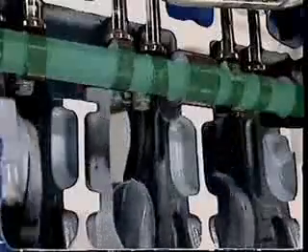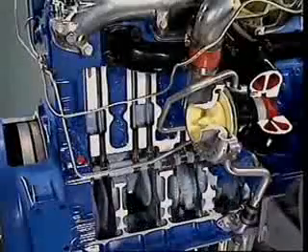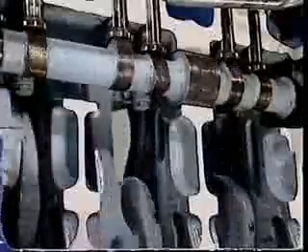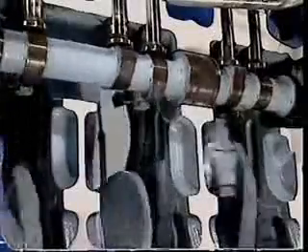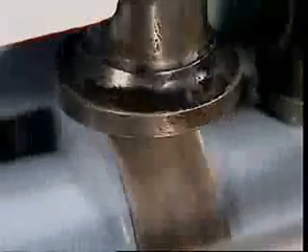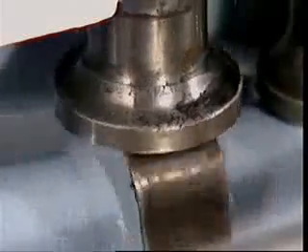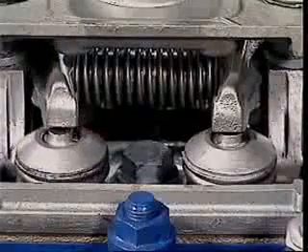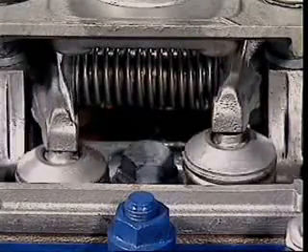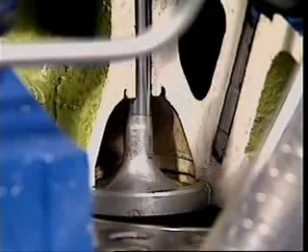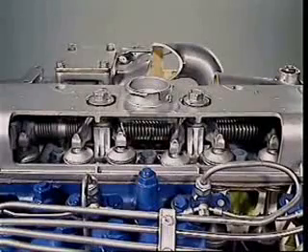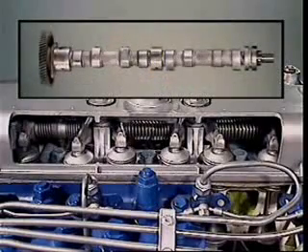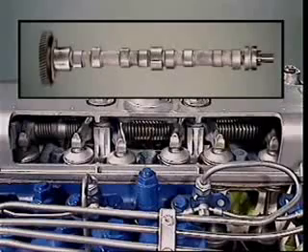In many diesels, valves are driven by a pushrod system. The camshaft is mounted in the engine block near the crankshaft and gear driven by the crankshaft. As the camshaft rotates, a cam bears against a cam follower that pushes up a pushrod. The rocker arm pivots and opens the valve. Some small, high-speed diesel engines use a camshaft in the cylinder head. This is called an overhead camshaft, and it's usually driven from the crankshaft.